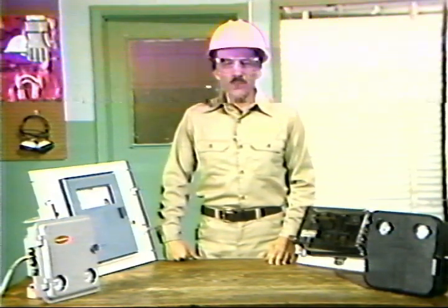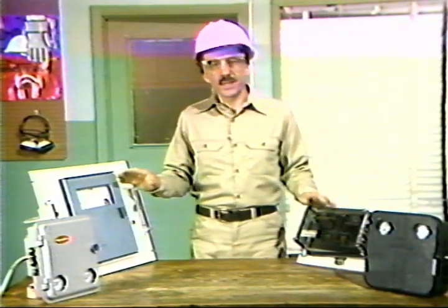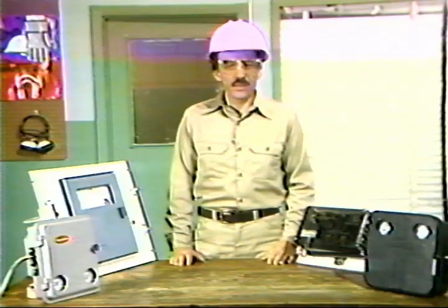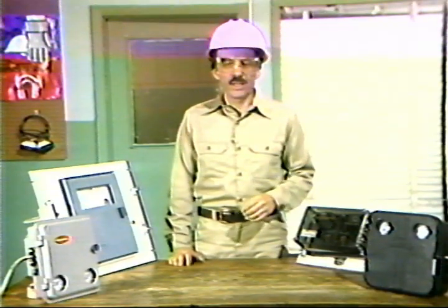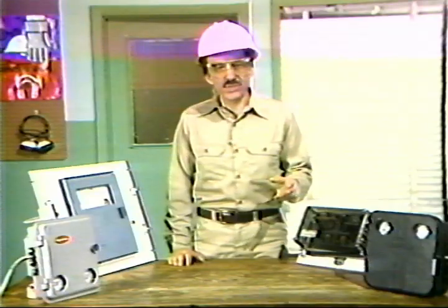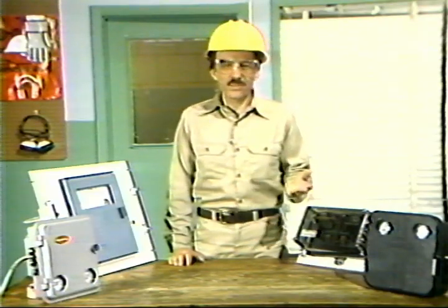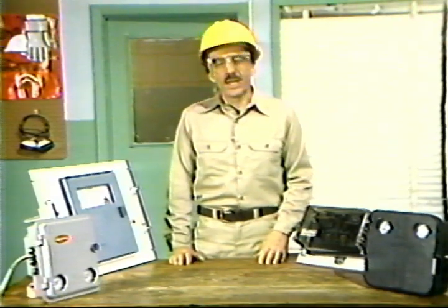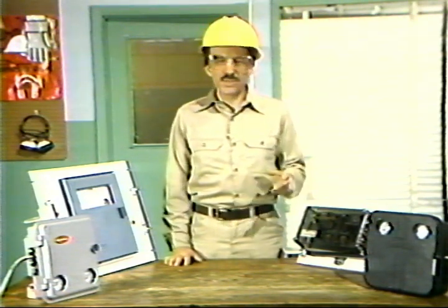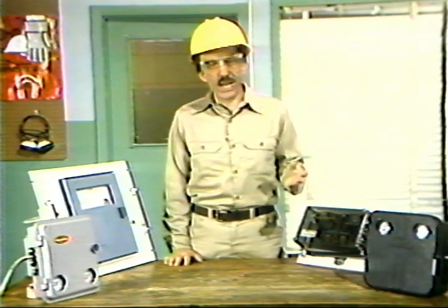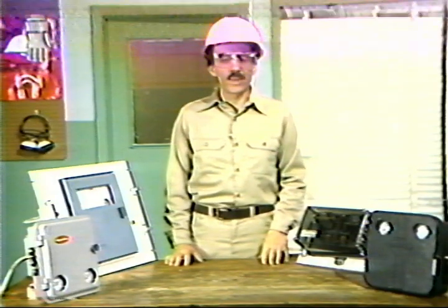For the most part, pneumatic controllers such as these contain the same basic mechanisms as other pneumatic instruments. They operate on the self-balancing principle. That is, they respond to changes in input by rebalancing themselves automatically. The new output from the controller reflects the change in input and causes the control system to attempt to correct the change in the process variable.